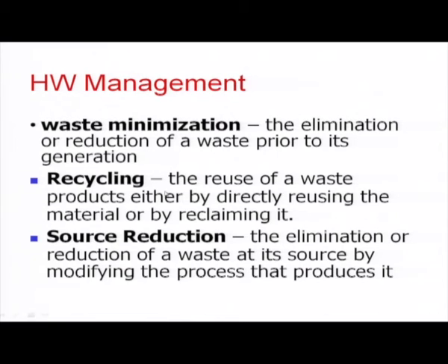Okay. That is a part of recycling. And then source reduction, the elimination or reduction of a waste at its source by modifying the process that produces it. So, waste minimization, which incorporates recycling and resource reduction, is something you have to pay attention to as a part of hazardous waste management, and this is really the best way rather than incinerate and then dispose of it.